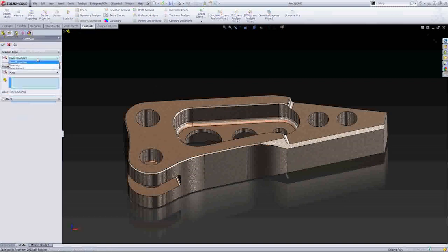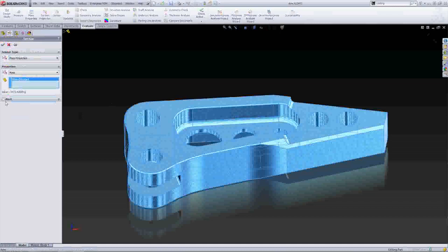We can use a nifty little tool inside of SolidWorks called Sensors. Sensors allow us to measure the mass or dimension of our part, and it will alert us if the value ever goes too high or too low for our liking. In this case, we'll set it for a mass sensor, so it will alert us if the part gets too heavy. Here, I will set the alert if the mass goes greater than 4,000 grams. So I can play with the part size, but it will warn me if I'm making it too heavy.